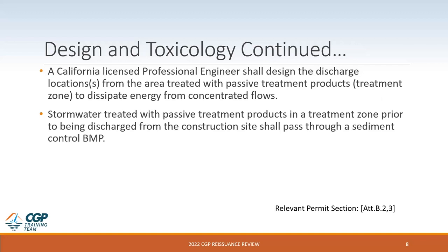So also with respect to the design, a California licensed professional engineer shall design the discharge locations from any location with passive treatment products being used to dissipate energy from any concentrated flows. And really the goal there is to try to provide additional opportunity for sediment to settle out after it's been bound with the treatment chemical, and also to prevent any potential discharge of unbound chemical from a construction site.